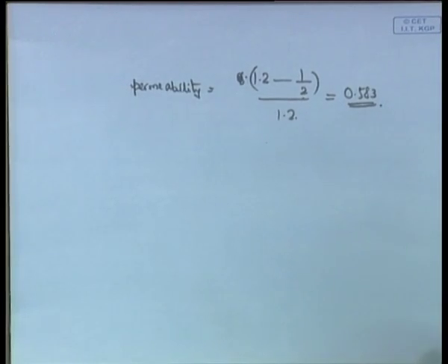What you need to know here is, remember that equation I wrote, which said that intact volume before bilging is equal to intact volume after bilging. It was like saying that the final weight of the ship minus the added weight is equal to the initial weight of the ship. That is that equation.